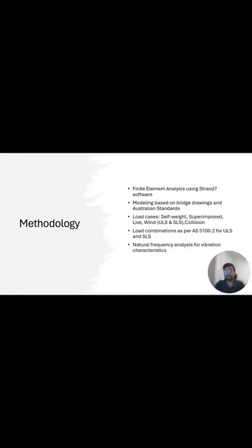First, we started by designing the model itself using Strand 7. The modeling was based upon the bridge drawings and Australian standards. We then calculated the load calculations and load cases: superimposed load, self load, live load, wind load, and collision load. Load combinations were as per AS 5100. For ULS and SLS, natural frequency analysis characteristics were also studied.